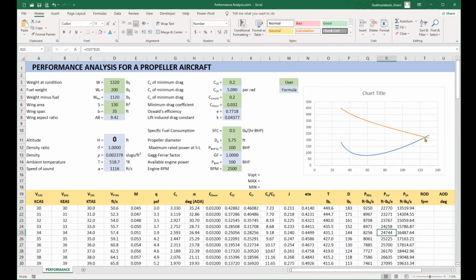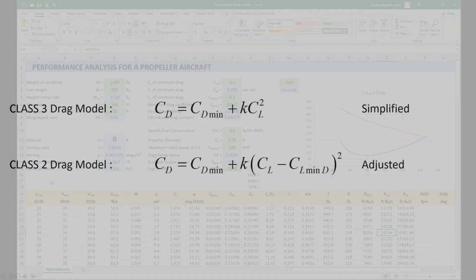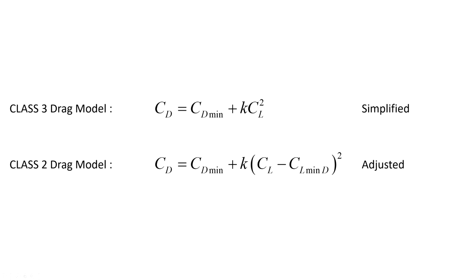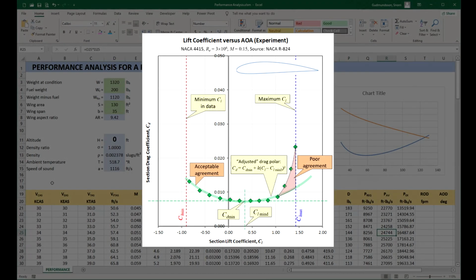The intersection of the thrust and drag forces over here represents the fastest airspeed the airplane can achieve at this altitude. There should be another intersection on the left-hand side, but it occurs at an airspeed less than 30 kCAS. Recall that assuming our stall speed will be 45 kCAS, that prediction is altogether incorrect. It shows the limitation of the adjusted drag model: it can't keep up with the rapid rise of drag as the airspeed drops. The simplified drag model is much worse in this capacity. You need to be aware of this shortcoming because it leads to awful low-speed performance predictions.